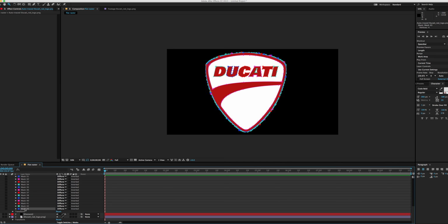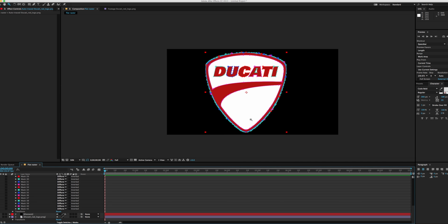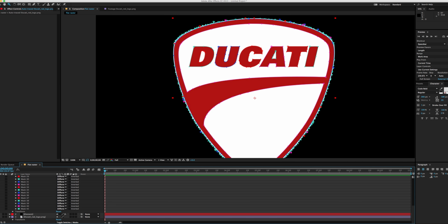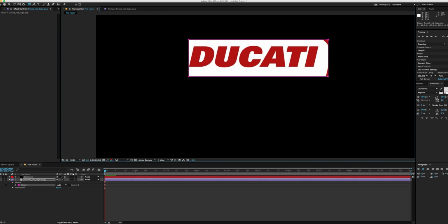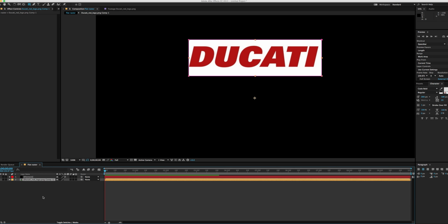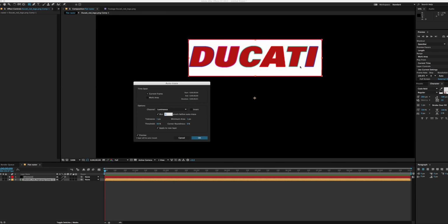Now in reality this isn't going to work out too well for me, because how do I know which mask is which? I could go through something like this if it had a better edge. If I was able to clean up that edge just a little bit, then I can go through and just mask out, let's say, this text. So in that case, what I might want to do is mask out just this text here, right? And then we'll pre-comp it. And the reason why I'm pre-comping that is so that way if I auto trace this now, it's only going to take this information.